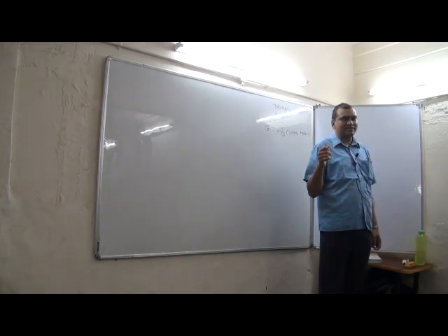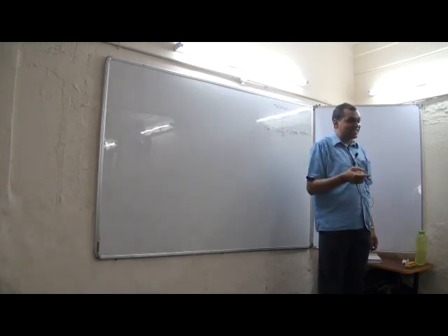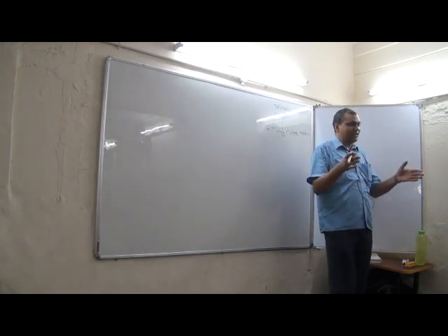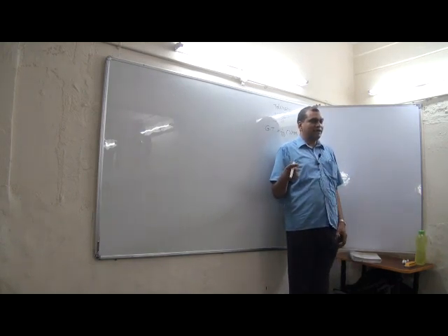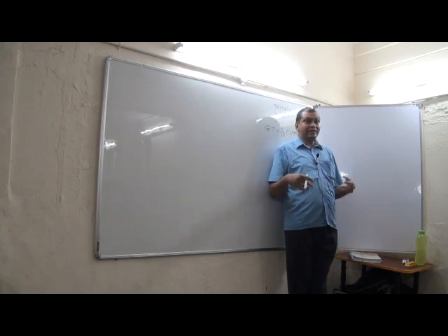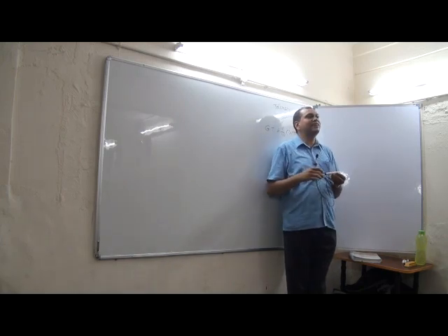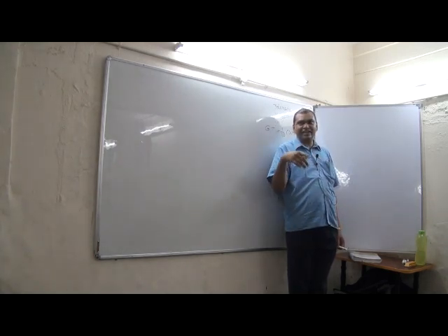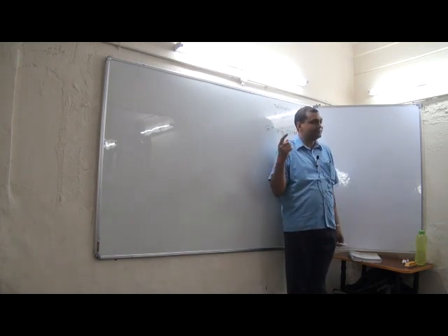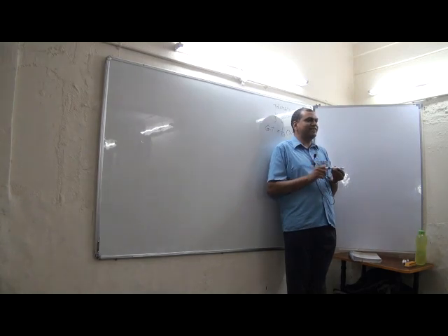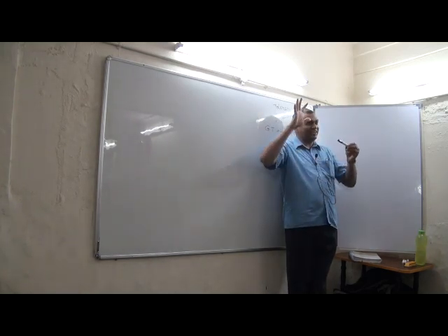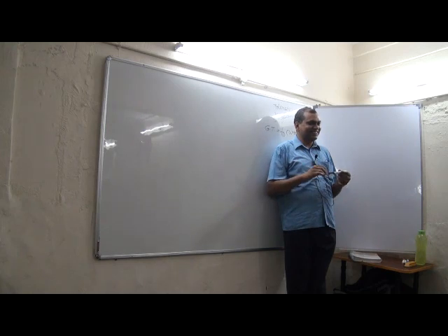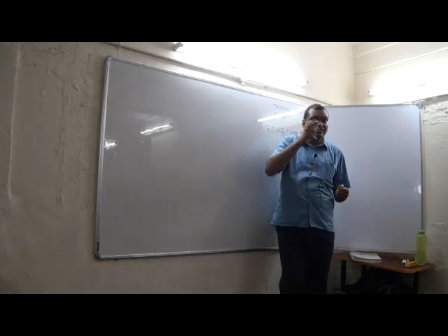Second statement of Taylor's principle: go gauges are used to check size as well as shape and have to be of full form. So let us say L is the length of the hole and X is the length of the gauge. X will be greater than L because it has to cover the entire working length of the hole, since it has to check size as well as shape. So the go gauge moves through the entire working length of the hole or shaft. Because shape means if the hole is slightly tapered, the gauge will get stuck. So that you understand that, it checks size as well as shape.